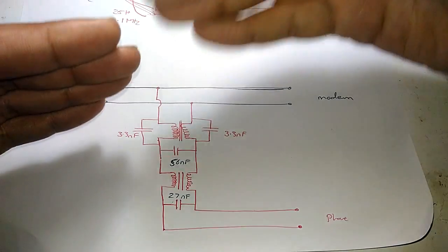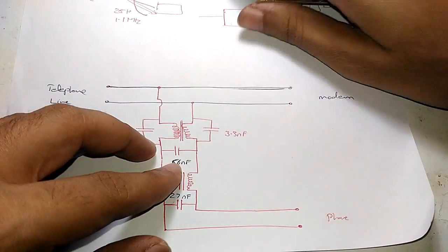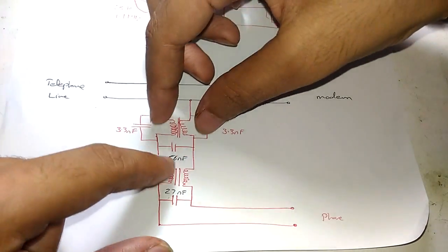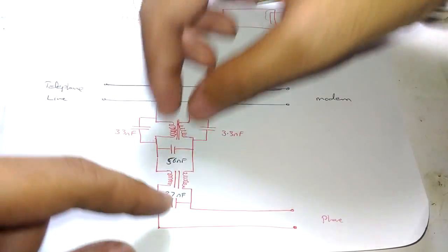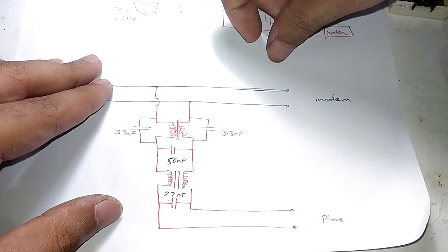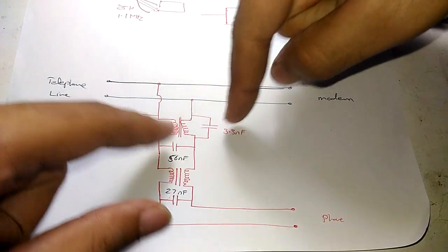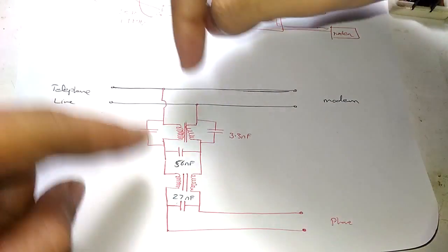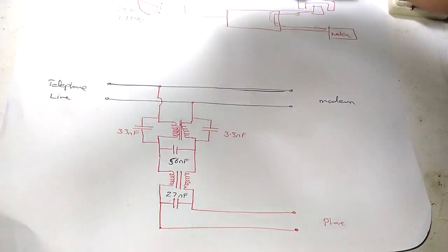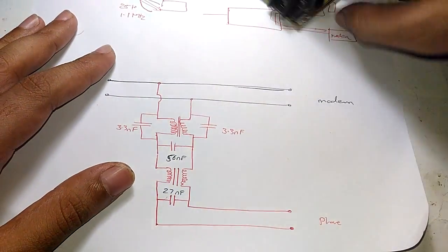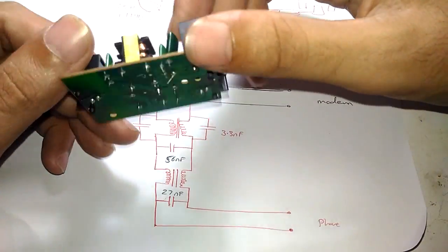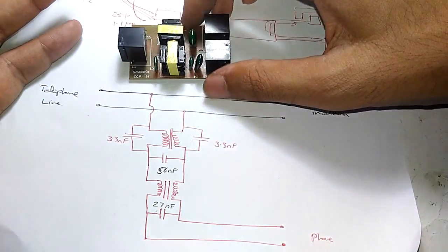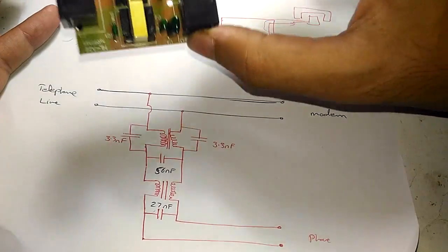But as the frequency goes up, this circuit kicks into action. It opposes those frequencies from getting into the phone line, and that way, if the high frequency signal by any means goes into it, there are two stages of filters, so it's going to effectively block the high frequency from getting into your telephone line. And after all this, your high frequency and low frequency can actually coexist in your telephone line without any issue, because of the presence of the filter and other things. So that is all about an ADSL splitter. Now I hope this video solves the mystery of why we need an ADSL splitter.